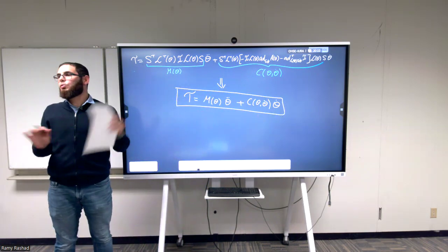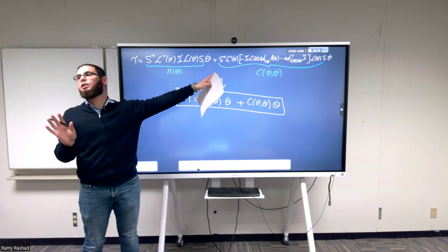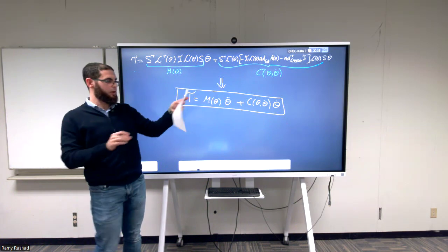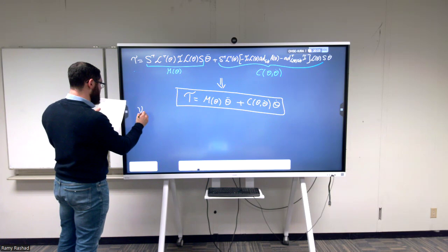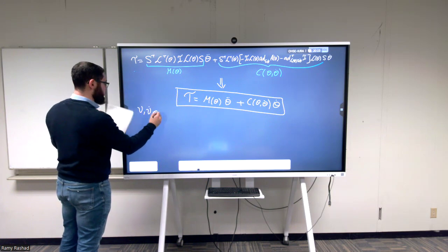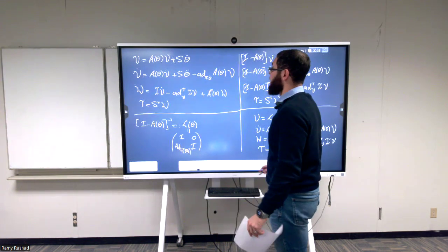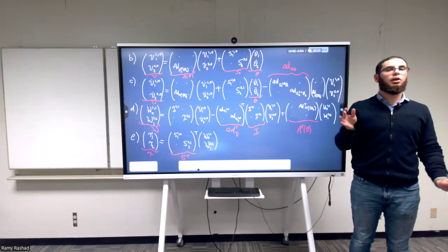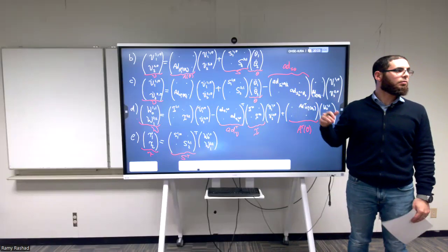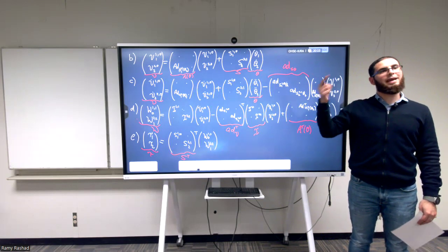Now let's look at the dimensions to make sure that we're doing everything right. Let's do a sanity check. What are the dimensions of V dot? Remember, if you go back here, what is the dimension of V in general, not just for the two-link manipulator? It's 6n by 1.